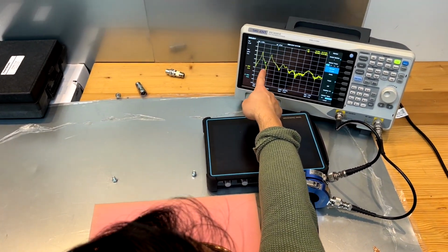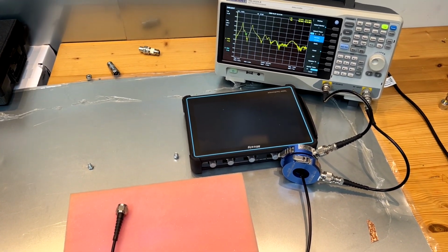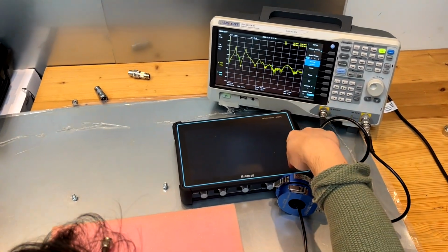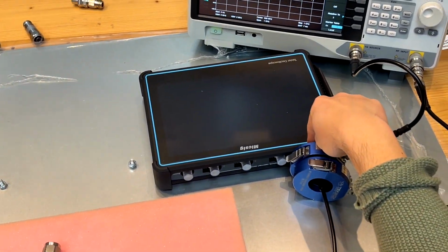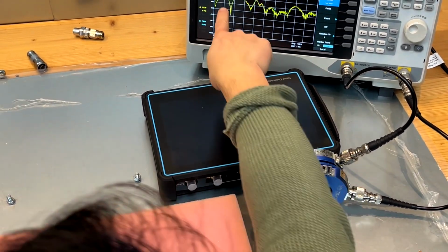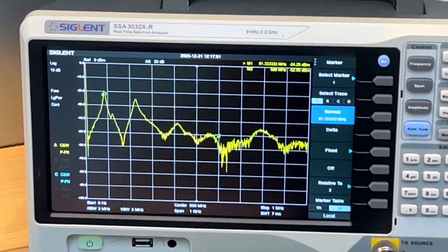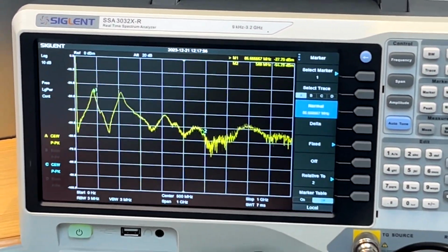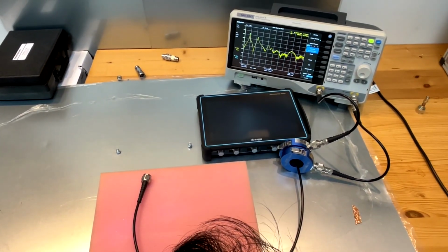So previously we know it's about 144 megahertz if we inject signals at the center of the cable as a half wavelength antenna. But now, because we are providing a lower impedance at this end, and we inject noise on this end, this cable all of a sudden becomes more like a quarter wavelength antenna. If you look at that resonance frequency, it becomes 86 megahertz. So this cable now acts more like a quarter wavelength antenna, okay?